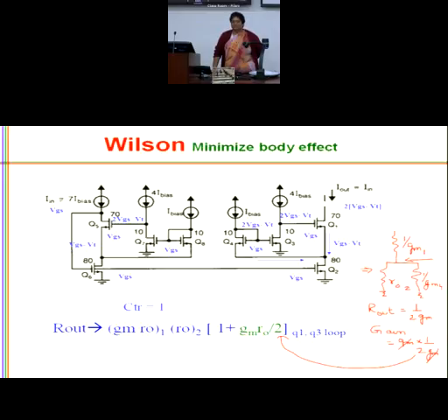So this is one advanced current mirror circuitry where you are getting a very low voltage requirement and you are getting a very high RI. And this is particularly useful to an op-amp to generate ISS where you are going for single output, because then your P node, VP node, it never comes to 0, AC ground.